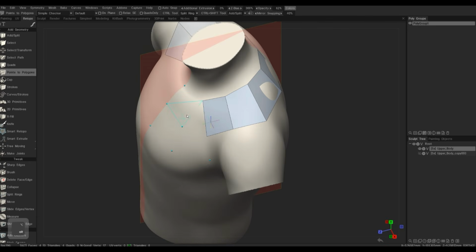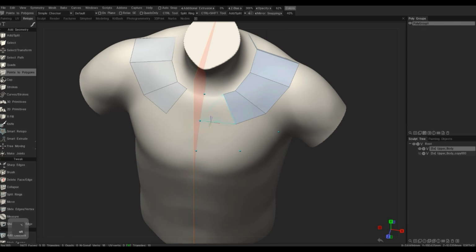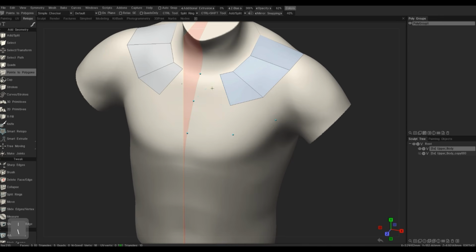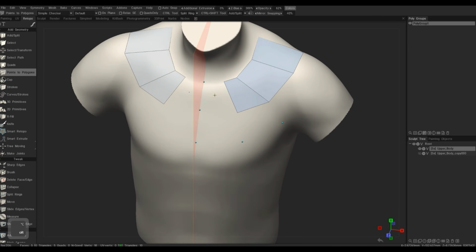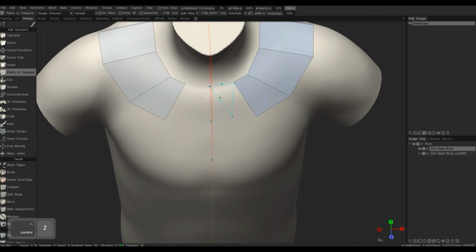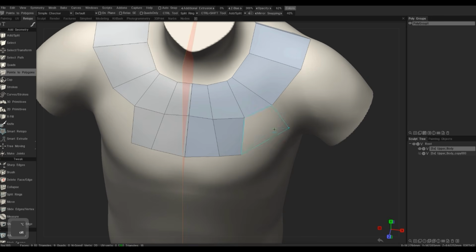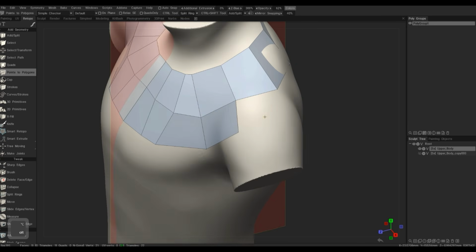It's important to have quads because if this is not a quad, if it's a triangle or an odd face angon, it will start to create holes. I'm trying not to catch the middle of the polygon to create the patch, so I'll kind of help. And then I press the right mouse button and I move these points around. It snaps over its symmetry. And let me go create this mesh.